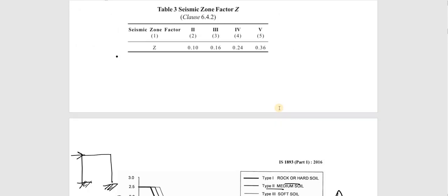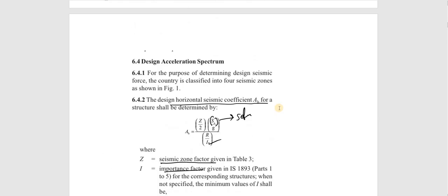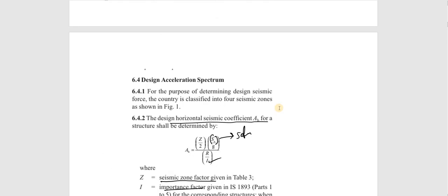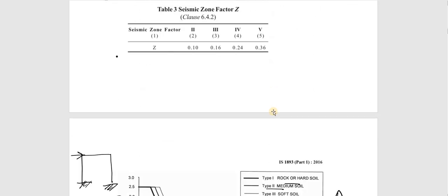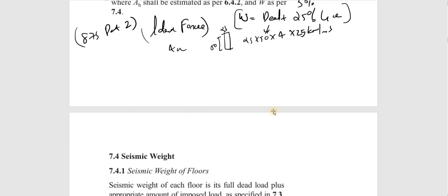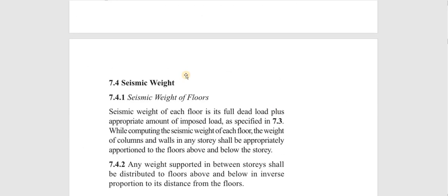So that is why we are using this response spectrum. Most of the time, if I am planning a building in Trivandrum, I can use a response spectrum only if I have a response spectrum plot of Trivandrum. Otherwise, I have to model. I will create a lot of models, give some random values, find out a response spectrum and plot it. From the response spectrum, I can find out the value of AH, and then the value of lateral force. That is how it is done in reality.